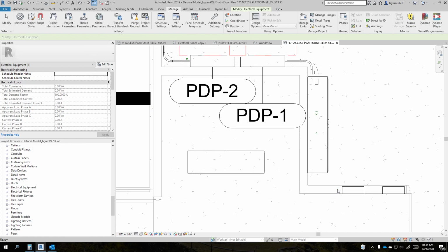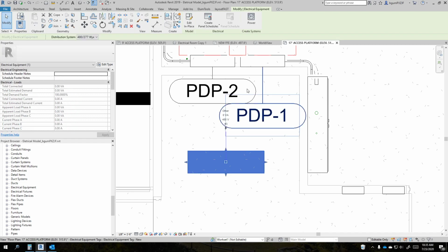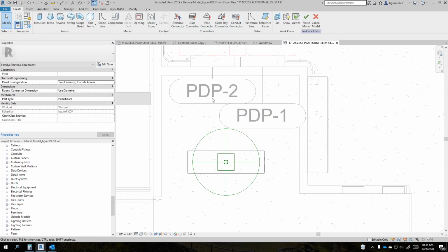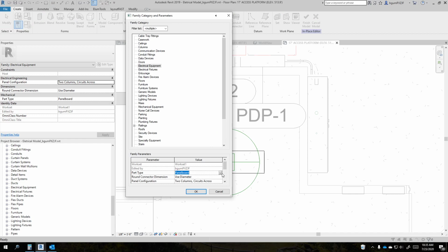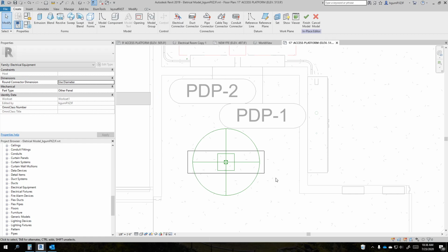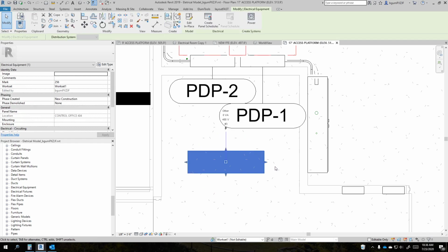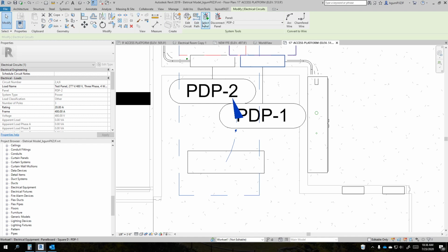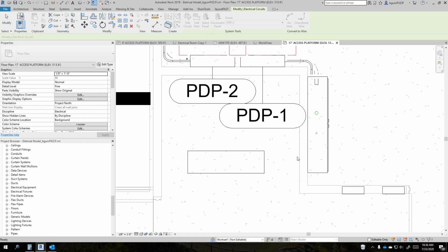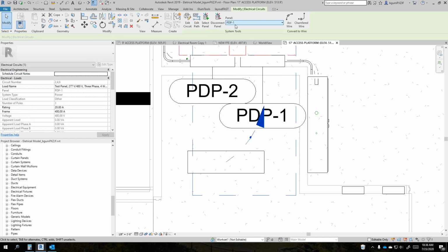So now we'll switch gears for just a second, and we'll see if I do an edit in place on this, and I just change the part type category to other panel. I select that. I do finish model. I believe that if I hit power here, I'm still able to select that it's fed from that panel, and see that worked.